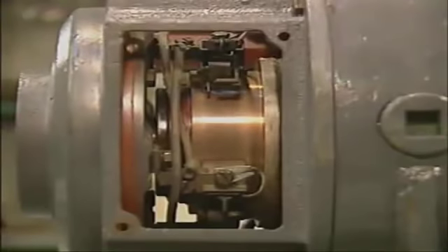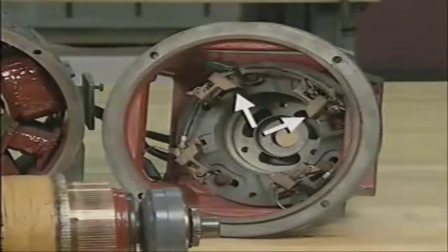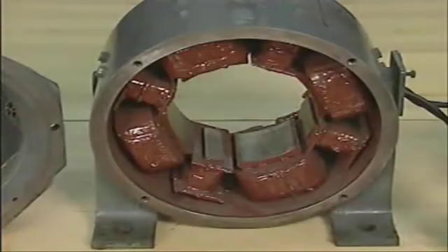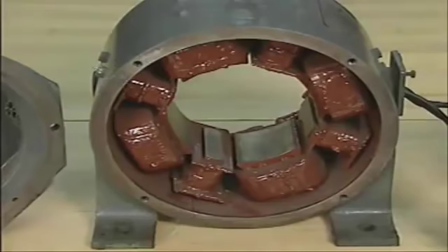Most DC motors have one set of brushes for each main field pole. There is a negative brush for each south pole and a positive brush for each north pole. In addition to the main field poles, this motor also has interpoles to help compensate for armature reaction. As is usually the case, an interpole is smaller than a main pole piece, and it has a coil wound around it. The interpoles are bolted to the frame.